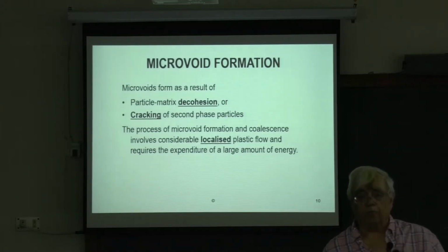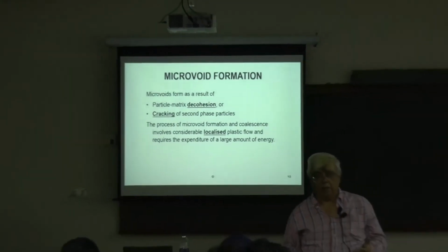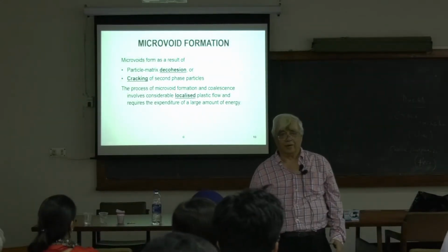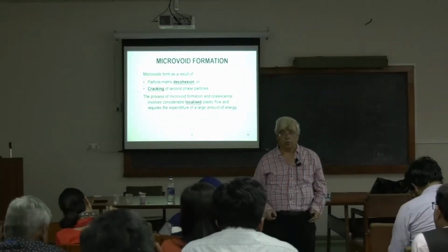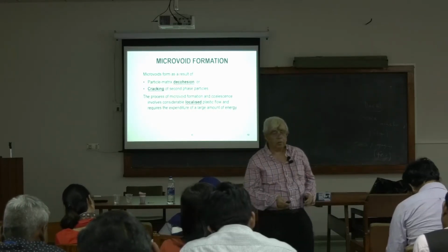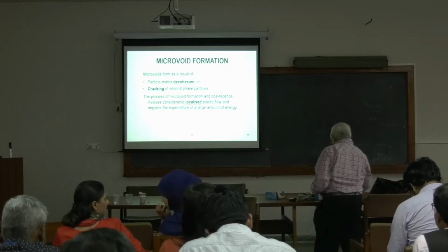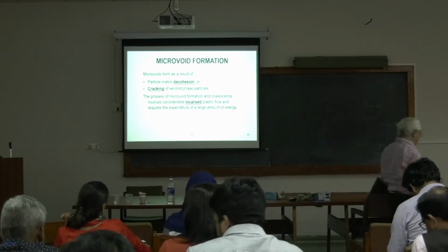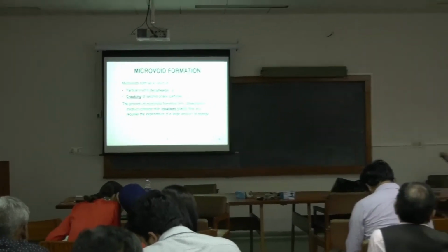If you put fly ash in this epoxy, you can make it tougher. So it's a very cheap material, and you use that epoxy to make the composites. It's short milled carbon fiber. Milled: it's a long carbon fiber, just cut into short pieces. Short milled. Do you want me to write it down? Milled is cut down.